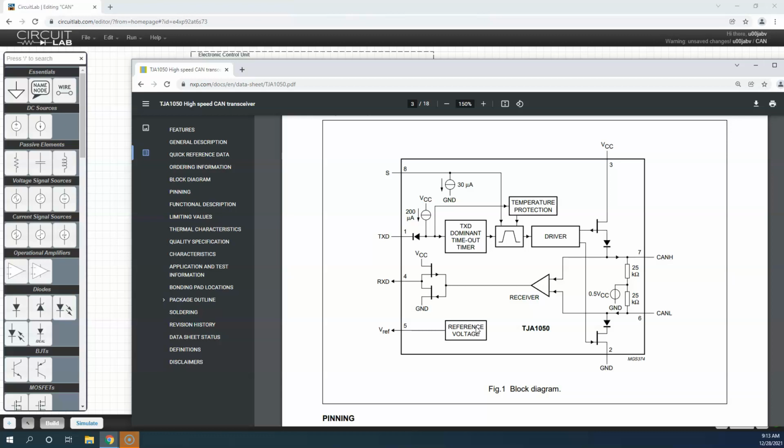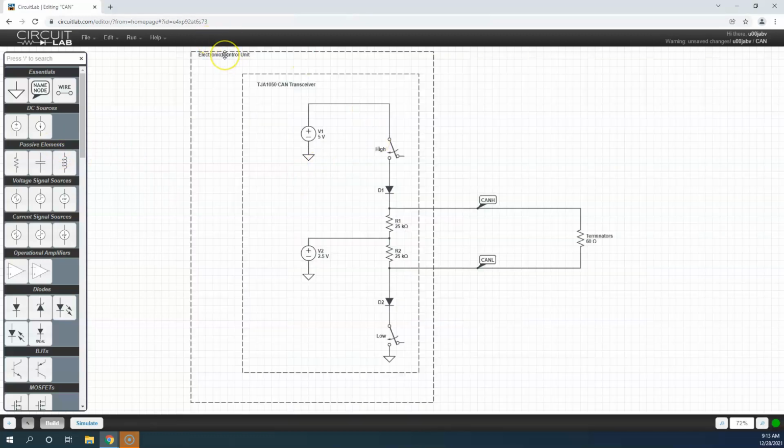So this is the device which is within the controller. It's contained inside of a typical controller, such as this generic electronic control unit that I have here. This could be an engine controller, this could be transmission, this could be a body controller, whatever it is. It would have contained in it one or more of these CAN transceivers. They may be from a variety of manufacturers, different part numbers from this one, but this is one which, as I indicated, is used quite frequently within the industry.